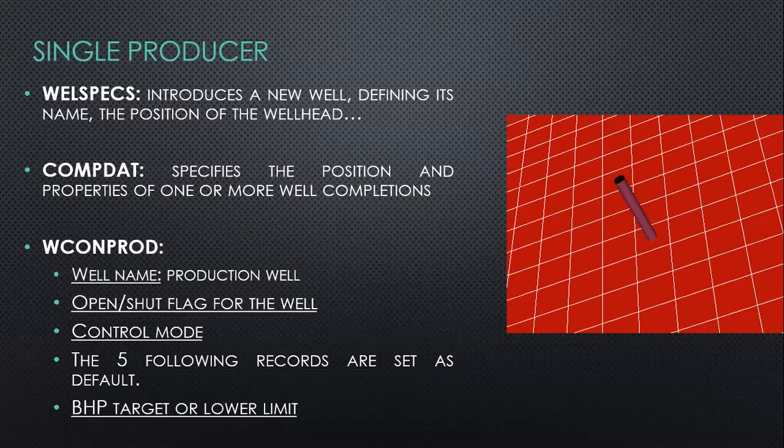It specifies the operations to be simulated, including production and injection controls and constraints, and the times at which output reports are required. Major keywords in this section are WELSPECS, which introduces a new well, defining its name, the position of the wellhead, its bottom hole reference depth, and other specification data. We also have COMPDAT, the completion data, which specifies the position and properties of one or more well completions, and so on.